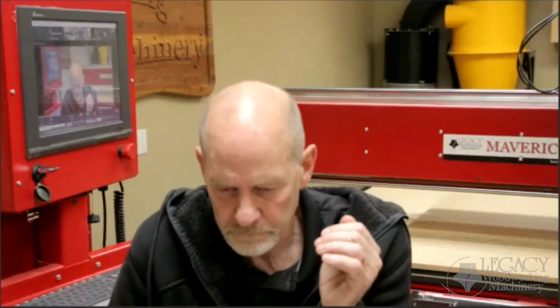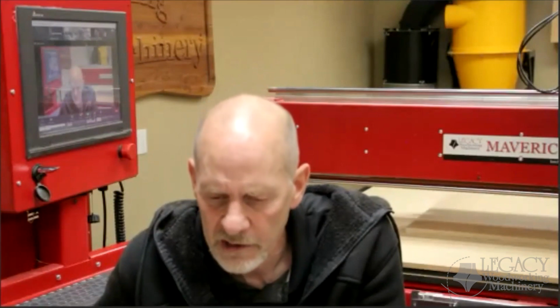If you're running several programs and the parts are the same thickness, Phil, can you do the multiple part touch off process on the first part and then not do the touch off again? Okay, no, Phil, you cannot do that. Let me make sure I'm not giving you bad information. You got to read your chat again. Oh, yes, Phil, you can. That's right. If they're all the same thickness, you do it one time. I misread it the first time.